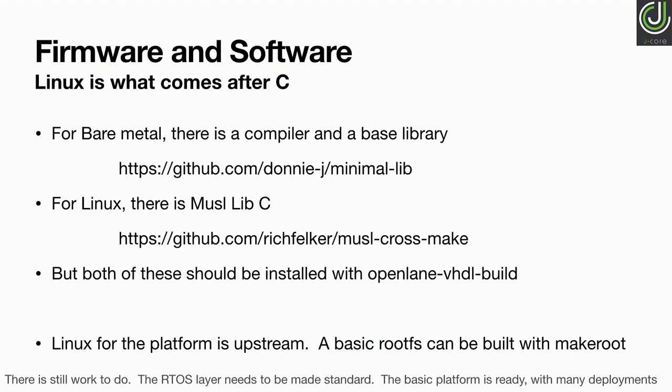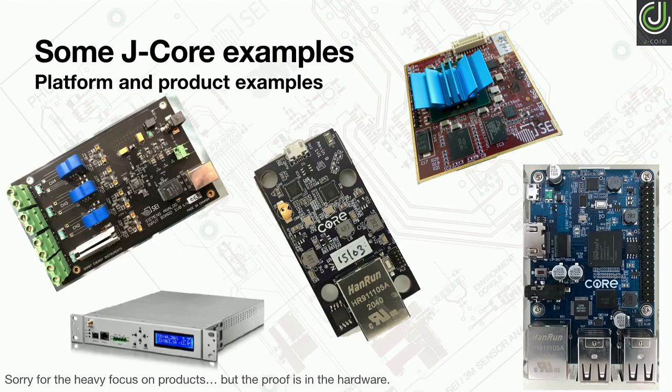Essentially, what that will do is get you a bare metal compiler with a bare metal C library, everything you need to write programs on a bare device in less than 200 bytes. Okay, so 200 bytes, not 200K, 200 bytes. So you can really do that in almost no space on your FPGA, or if you have a very small C RAM block on your ASIC.